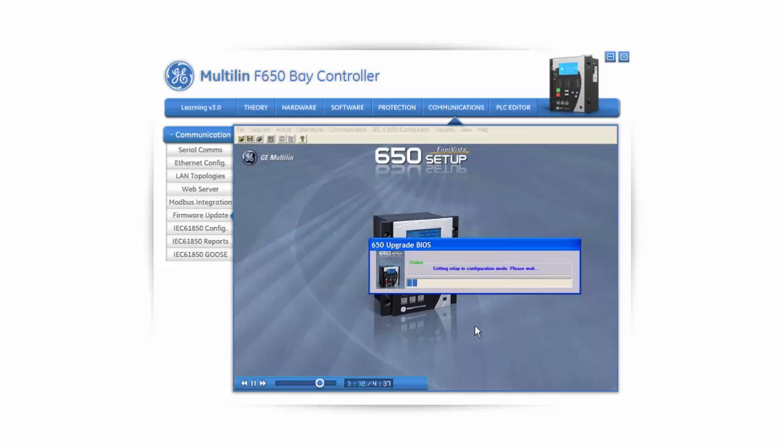In case this time expires or the relay is stuck after switching it off and on, the program will suppose there is an error in the serial connection and will show a window prompting the user to try again or postpone the process. If you postpone the process, the previous operating system and firmware will remain installed. Bear in mind that the serial COM port used in the boot upgrade procedure is the one selected before.